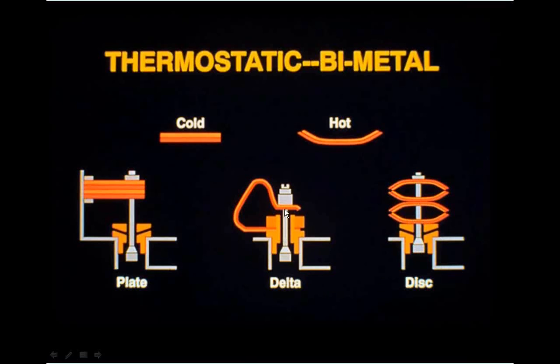The delta one we're going to go into a little bit more detail because that uses temperature and pressure, but the same principle is true. As this element heats up, it pulls up on the stem to modulate that particular trap.